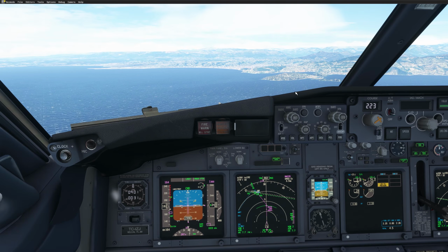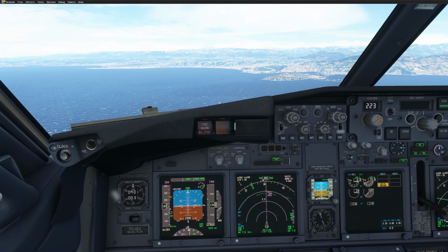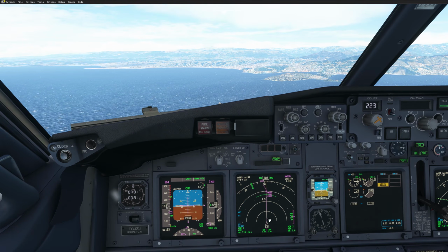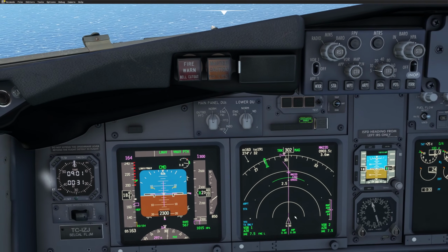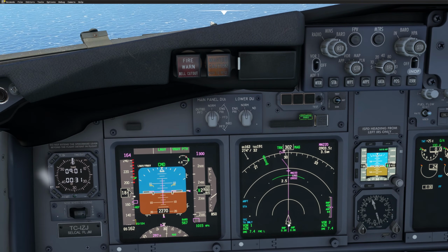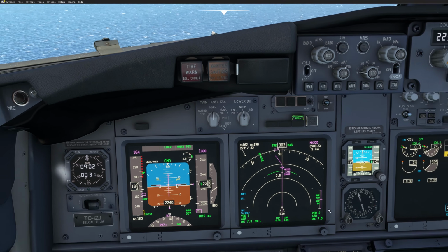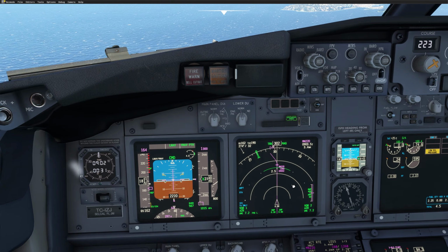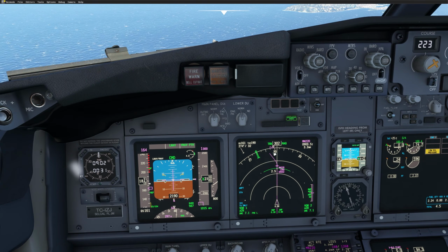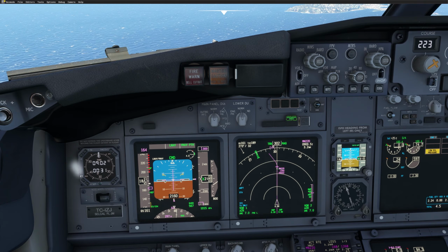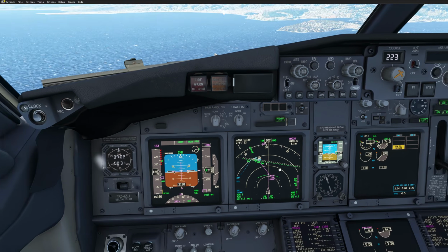Okay, let's get ready here. You are descending nicely on track. As you can see here, the deviation is good. No deviation vertically, no deviation laterally. Vertically, sorry. And once we reach that point, we need to continue on 303 to go to the runway.